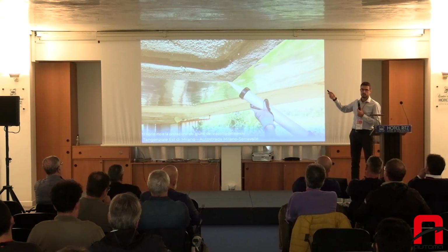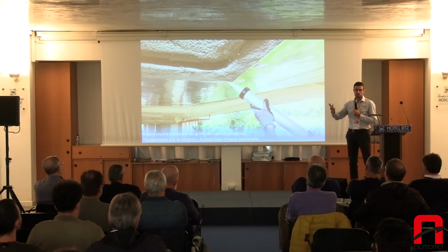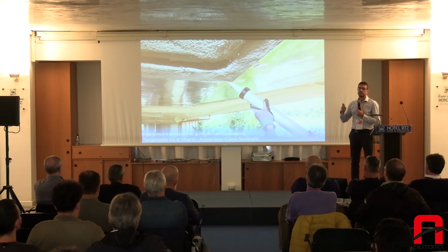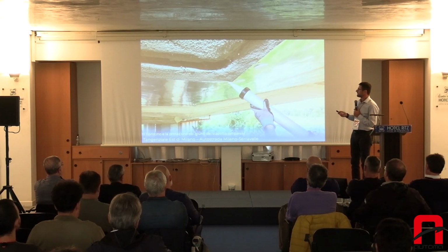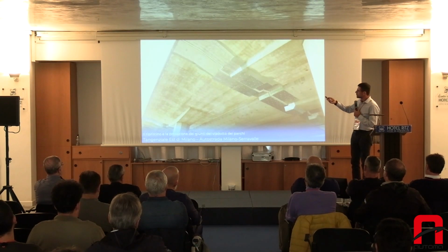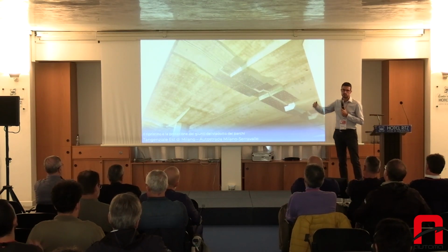You should also seal the sheet's perimeter because the back of the sheet has a gel that allows adherence of the sheet, but it's a water-soluble gel, so you need to seal the perimeter of the sheet to avoid water infiltration. Here you see the joint after applying the cathodic protection system.